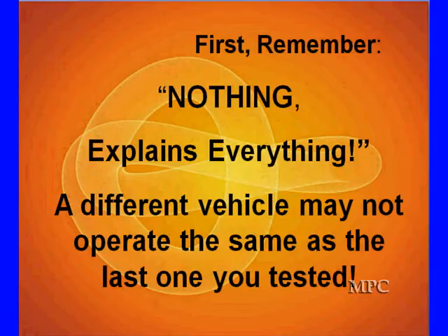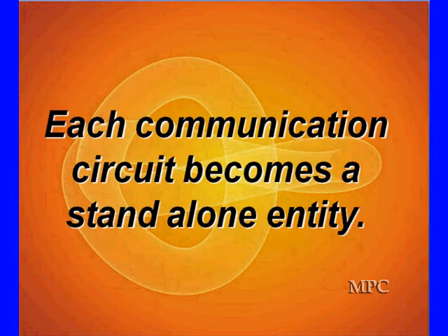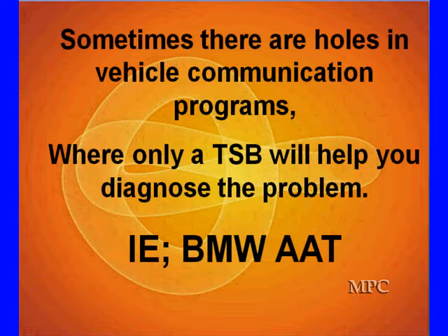But something we want you to remember: nothing explains everything. A different vehicle may not operate the same as the last one you just tested. Don't think because you know something in one place, you know it everywhere. Each communication circuit becomes a standalone entity that you're going to have to diagnose. And sometimes there are holes in communications programs where only a TSB will help diagnose the problem.